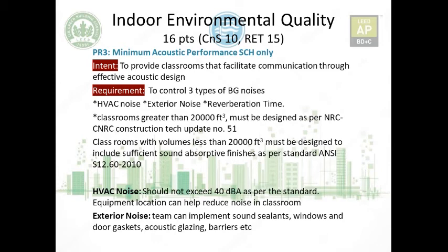Now when it comes to the exterior noise, the team can implement sound sealants, window and door gaskets, acoustic glazing, and barriers. These are all strategies you can use to dampen the exterior noise and fulfill the intent of this prerequisite.